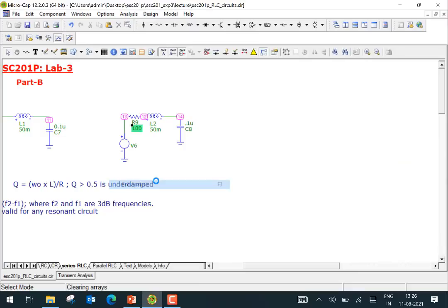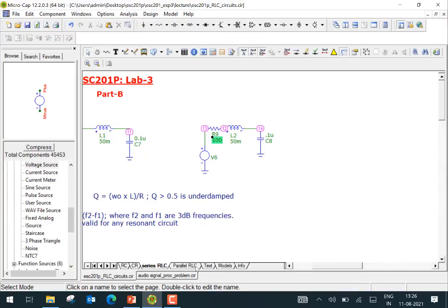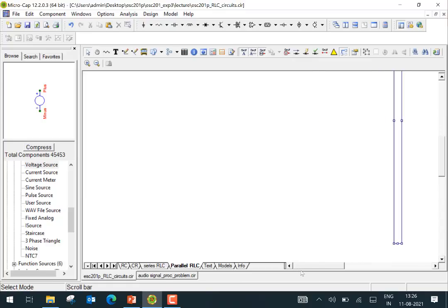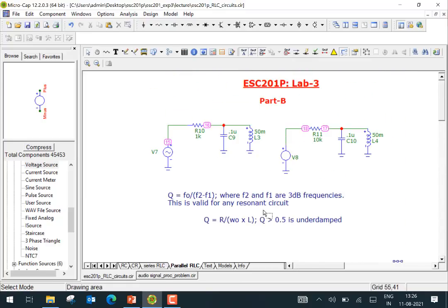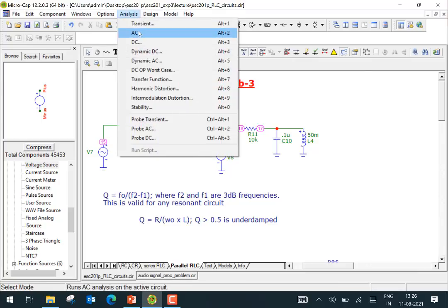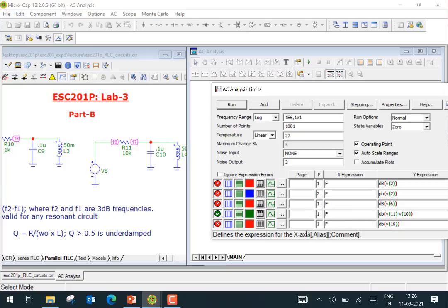And something similar, the complementary part, is the parallel RC circuit here, right? So this is the parallel RC circuit. All right, so this again, as we said, we'll explore in the frequency domain, and we'll explore in the time domain here. So the node to monitor is V16. So let's do the AC analysis here. V16 here. Let's disable this and enable V16 here in dBs.